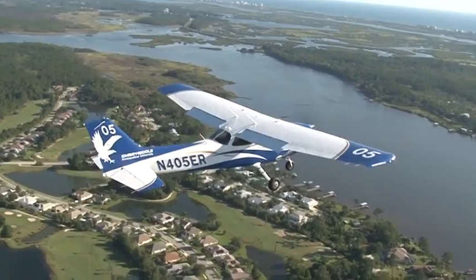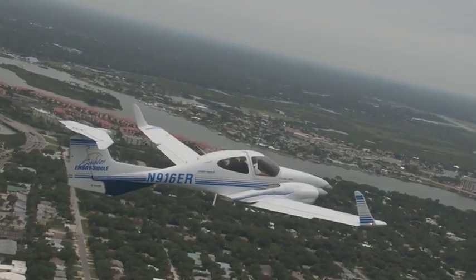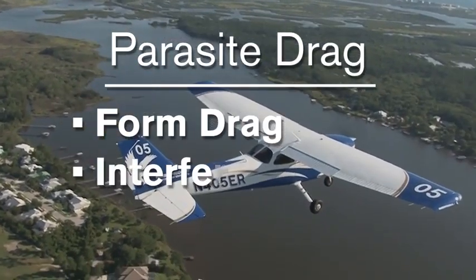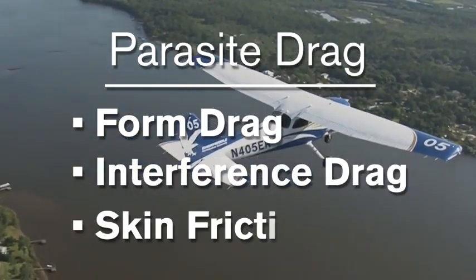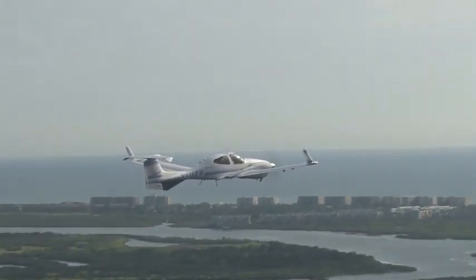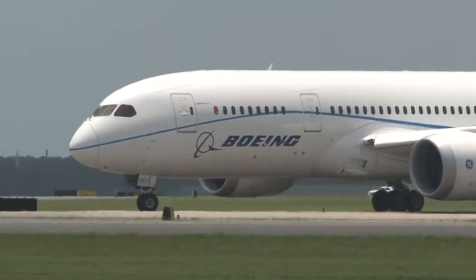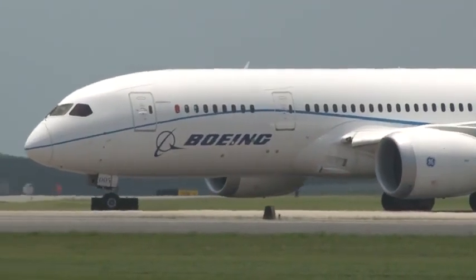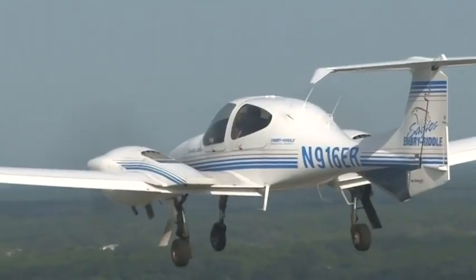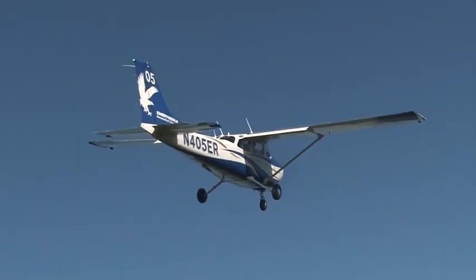Parasite drag is a direct result of the air resistance as the airplane flies through the air. There are three types of parasite drag: form drag, interference drag, and skin friction drag. Form drag results from the turbulence created as the air tries to flow around the aircraft. Aircraft with larger cross-sections will have higher drag than thinner, more streamlined designs. Other items, like the landing gear and the antennas on the aircraft, will also create form drag.